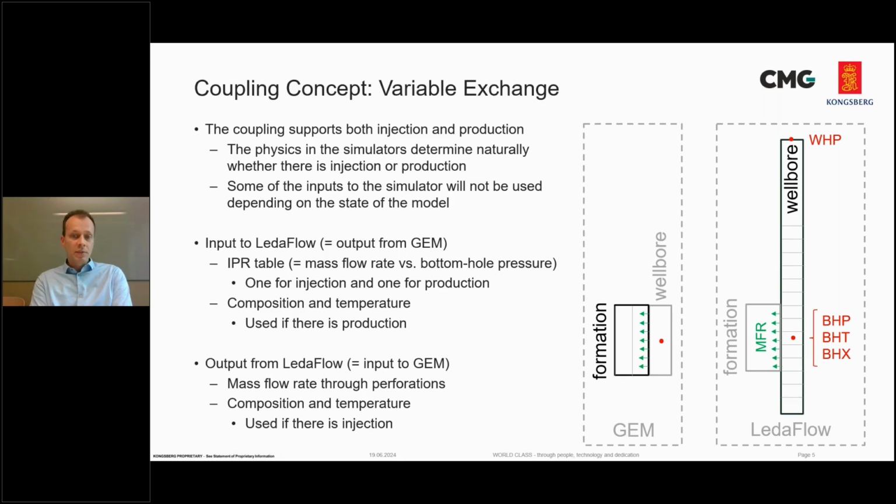And then the LedaFlow domain doesn't really simulate the formation, that is handled in terms of an IPR. But LedaFlow has a very detailed discretization of the wellbore, where we define the wellhead pressure at the top and the bottom hole pressure, temperature, and composition at the bottom. And so those define the different variables.